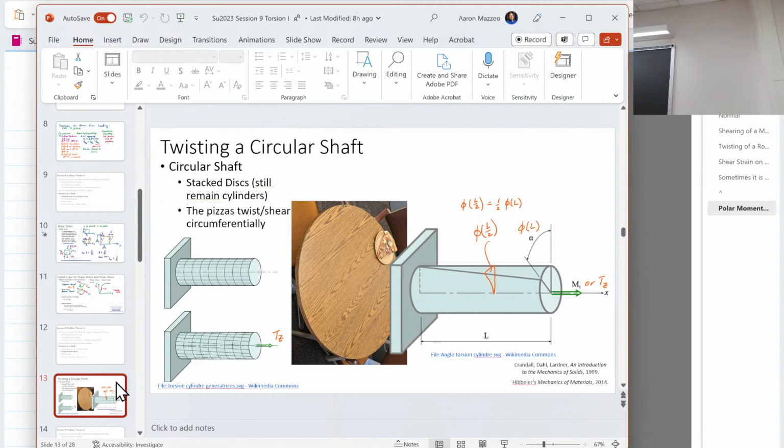The safety wire doesn't do anything in terms of tightening it. If the bolt isn't tight, the safety wire won't fix it. It doesn't actually add any extra tightness, it just keeps it from coming out. That's the whole safety idea. Okay, good, thanks for bringing that up.